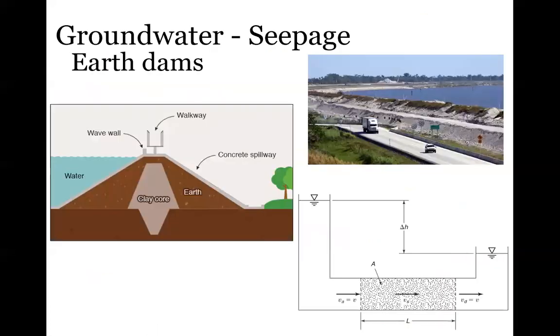This is also a recap. I showed these pictures before, but these are some of the real applications of why we need the permeability coefficient. A lot of times, especially in Florida, we want to design soil to either let water flow through it quickly, if we want to control flooding that way, or on the other side of things, we want water to not flow through the soil. So usually we have these two extremes of permeability that we care about.